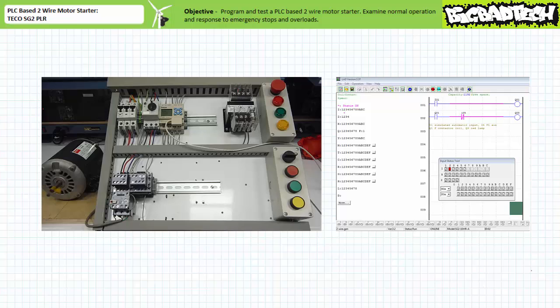Let's now examine its behavior during emergency stops and overloads. When the selector switch on input 1 is closed, the F contactor coil is energized, the F primary contacts close, and the motor turns on. Again, you'll note the red pilot lamp briefly blinks on, indicating there's a transitory period that output Q1 is being asserted and the F contactor hasn't fully closed.